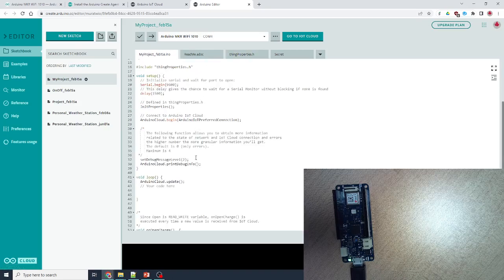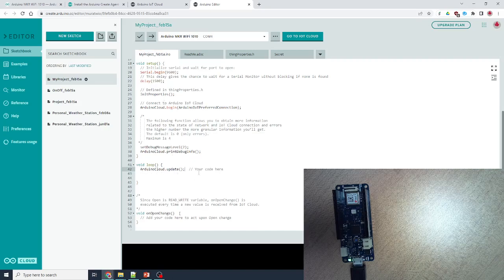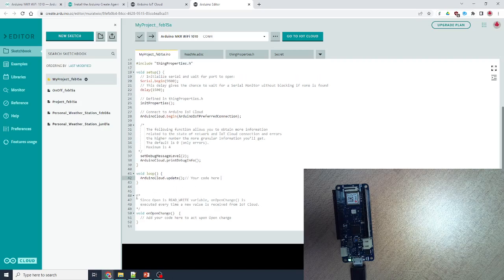So let's go to our function. Here is our function. If you want to go into details, you can look at it. There is some setup, and these are standard things. I just wanted you to focus over here, on this part. So what is my plan is this. If open, I don't need to say if open is true, right? Because it is boolean. So if it is open, I'm going to digital write to what? An LED built-in, which is 6 for this one, but why memorize anything? LED built-in, and it should be high when it is on.